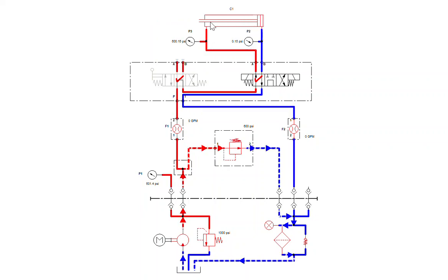That's very strange. The difference has to do with the volume. In order to retract the cylinder, the pump needs to supply a volume to go into the retract chamber. And it's basically a volume that's shaped like a cylinder of oil that's hollow in the center where the piston rod is. So while the flow is going in to fill up this volume, a larger volume, a solid cylinder of oil, so to speak, with no hole in the middle, is coming out at the same time. It's called flow intensification, and it has some implications.